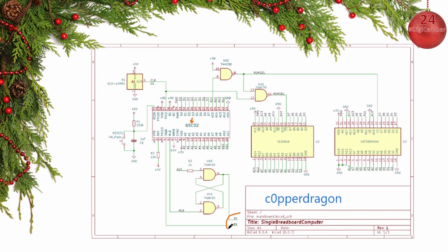They have some serial mumbo jumbo down here for TX and RX, probably to input data or something. They do have a reset circuit that is very similar to ours. They actually have a reset button here that shorts out this capacitor without a resistor. I think I would have done this to make sure that this capacitor and the switch don't get fired up. And they also have made a very simple chip select here to do this.